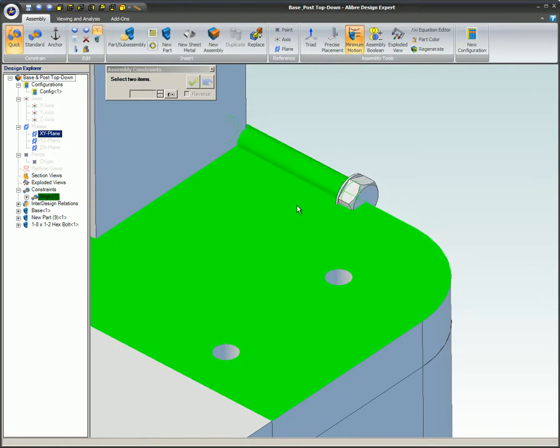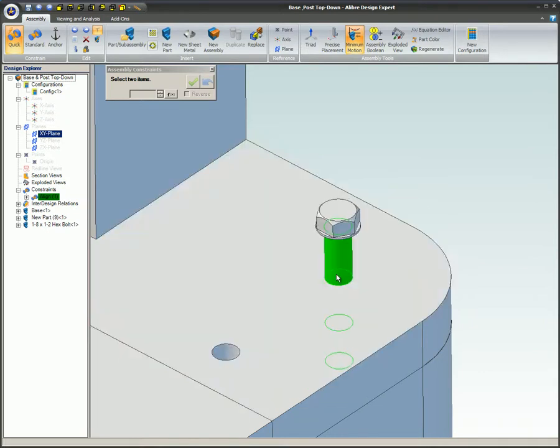What you hover over will change, and as it does, so will a constraint preview. In this example, we want to insert the bolt into the hole. While dragging the bolt, we will hover the mouse over the interior cylindrical face. The bolt will orient itself appropriately when we do this, and the interior cylindrical face turns green. When the constraint preview is what you want, release the mouse.